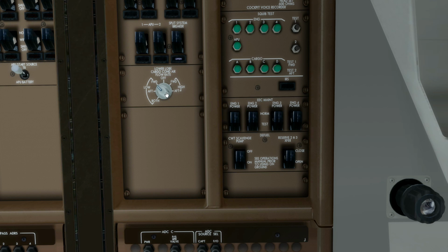In the low position, the forward low position, then Pack 3's air is going to both the main cabin, upper deck cabin, and all that good stuff, plus the forward cargo hold. Aft, we've got Pack 2. Pack 2's air is split into going to the main deck cabin and the rear cargo hold. And in both, we've got Packs 2 and 3 working in conjunction with Pack 1 to air condition the entire cabin, plus the air from Pack 2 is going to the rear cargo hold, and Pack 3's air is going to the forward cargo hold.